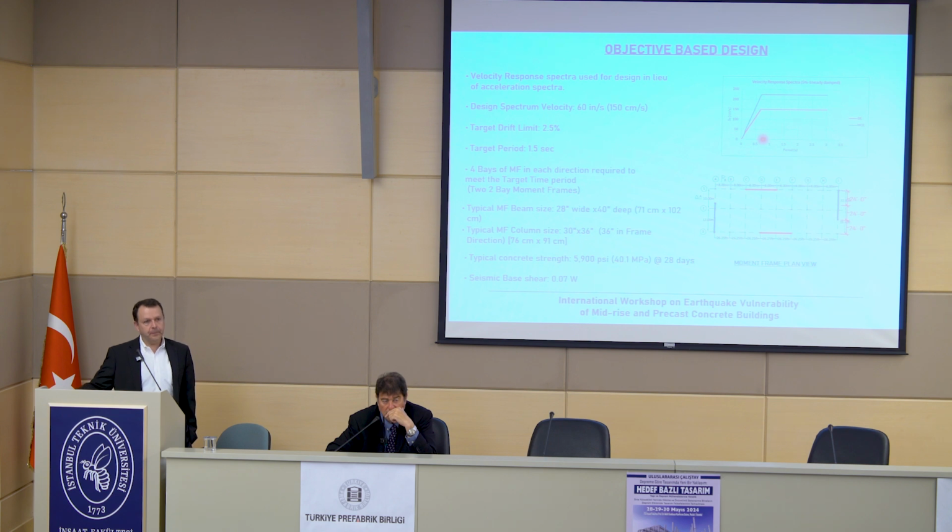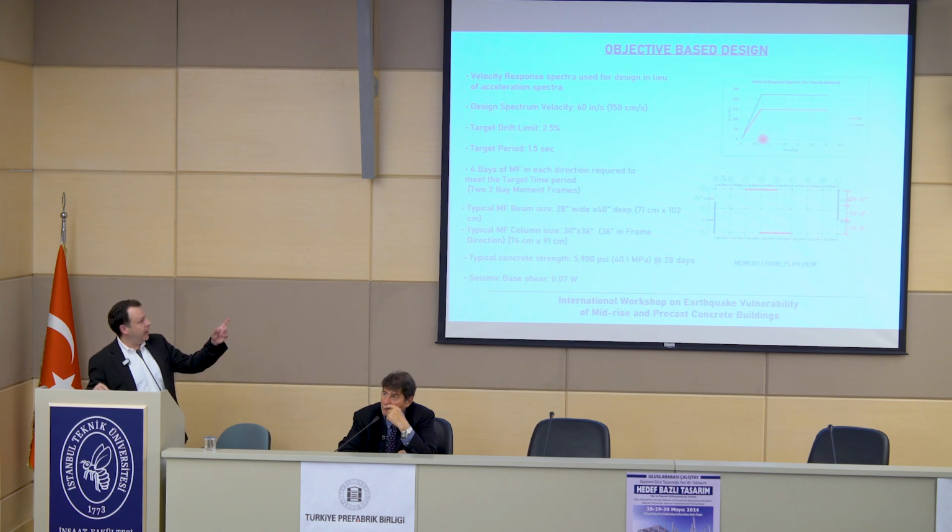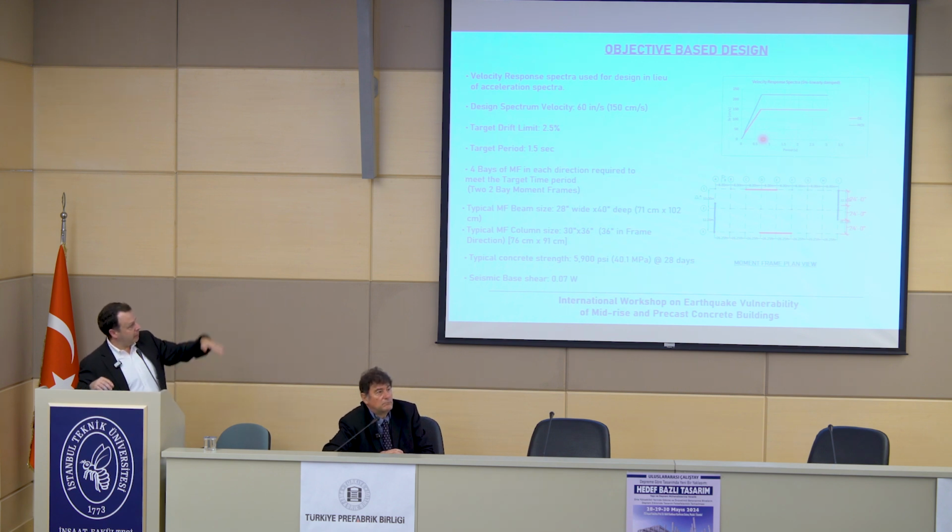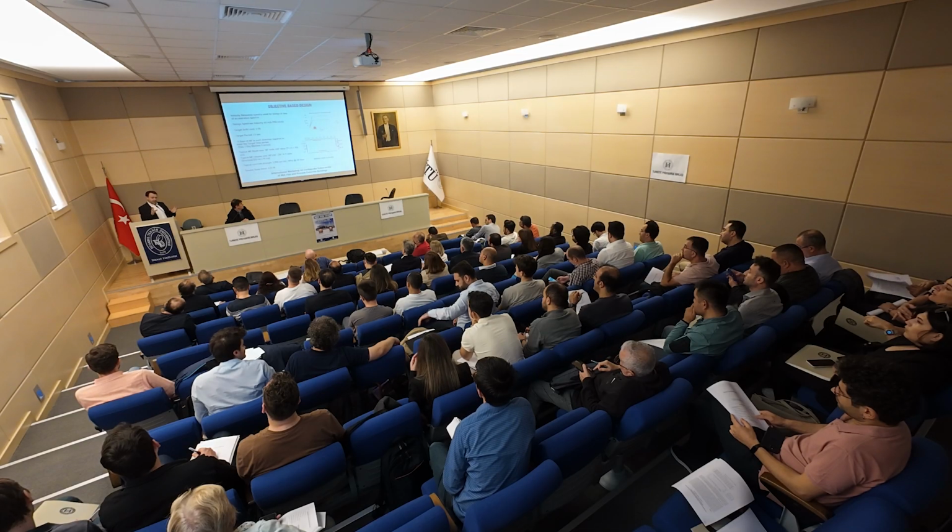Yeah, so we would have to check the diaphragms, right, and design the diaphragms as well. If you look at the dimensions that we would have, the diaphragm in the x direction is not flexible, and can be considered rigid. The diaphragm in the north-south direction would have to be considered as flexible, and then we design for it.